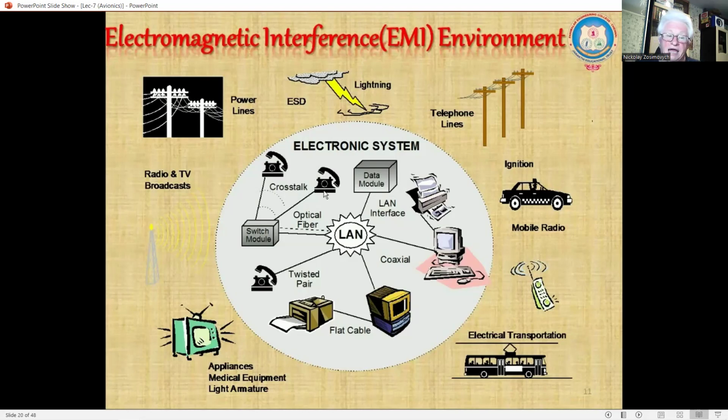Another source is the vicinity to a nuclear explosion and the consequent emission of gamma radiation and EMP of very high electric field strength. Military avionic equipment is specifically designed to survive up to a certain, classified level of these effects. This attribute is referred to as nuclear hardness and is achieved by the design of the circuits, use of nuclear hard components, circumvention techniques, and very efficient electromagnetic screening.